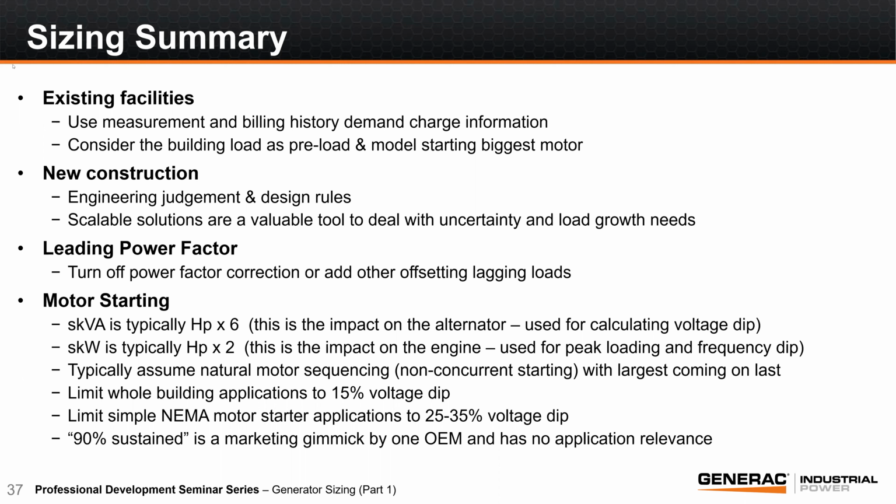Great. We had a question come in about derating. It's two parts here. The first part is, does Power Design Pro handle derates for altitude and temperature if entered in? And the second part is, if you're not using Power Design Pro, how do you manually derate for altitude and temperature? So yes, Power Design Pro will allow you to input things such as your altitude and your ambient temperature and things of that nature. And it will take those factors into consideration when outputting the recommended generator size.